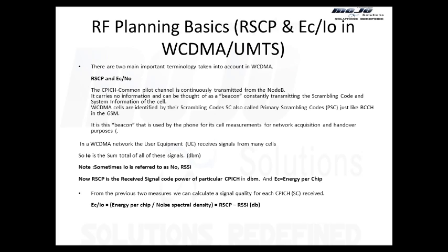The UE always measures coverage and makes its decisions for handover and other things based on it. There can be many different parameters to predict coverage, like RSSI, RSCP, or something else as well. But what is used by the system to make decisions for handover, quality, and coverage is called, in UMTS, RSCP. RSCP is received signal chip power. Well, what is received signal chip power?